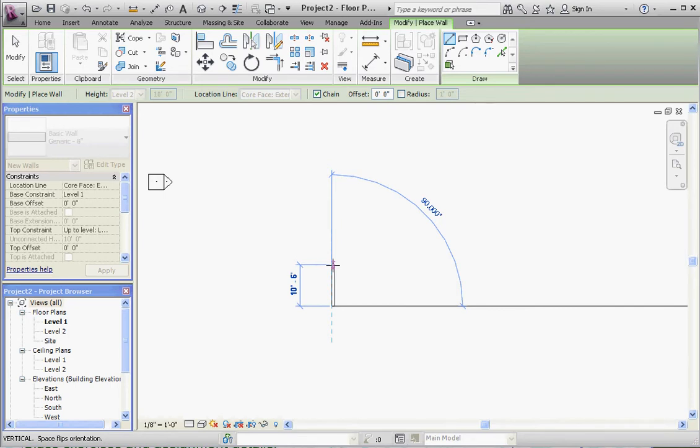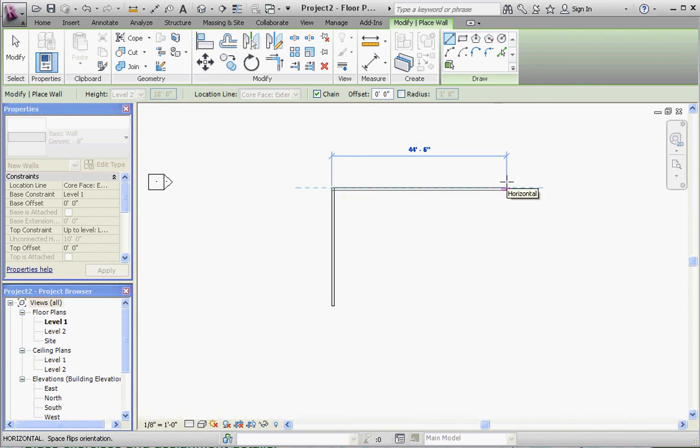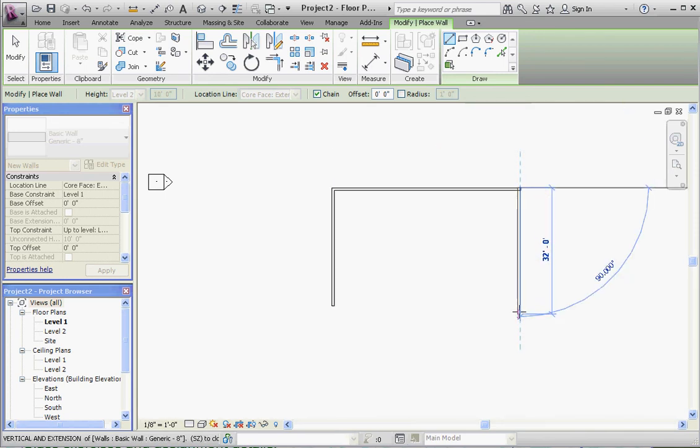So we're going to draw a line out maybe 30 feet. So we'll draw that line up about 30 feet. It's in there somewhere. Draw a line over. We'll just make somewhat of a square. And just like with AutoCAD, we can pick up that polar tracking, that horizontal dashed line that you could see, and bring that over, and we'll connect our walls, and that completes it.